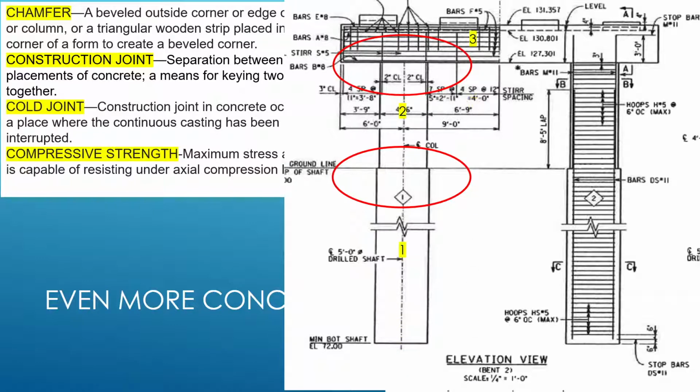Three pours. And what they'll do is, when you finish one pour, you'll scar up the top, take some piece of rebar or something and dig gouges into it, so that when the next pour is poured on top of it, and you either apply an epoxy or a moose milk, as some states allow, the concrete will go into those keyed areas, those grooves that you cut, and give a good bond for each different pour.